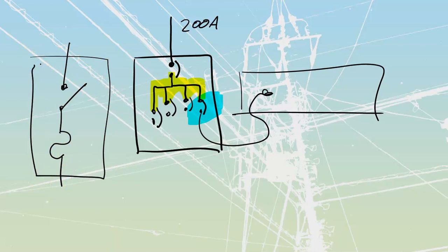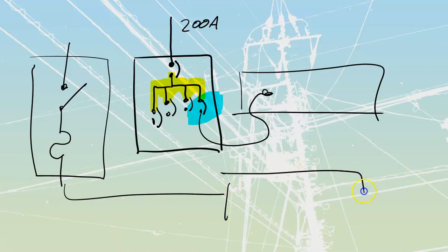Fusible disconnects come in our three-phase standard values of voltage and current. They sometimes have neutral blocks included with them. In a lot of cases, three-phase fusible disconnects don't come with your neutral block, and if you have a 4-wire or a Y-type, you need to order that separately.